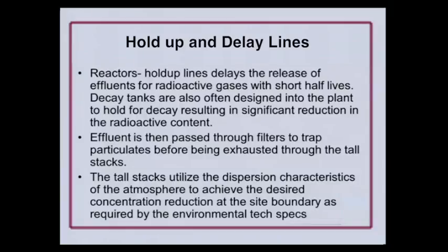The length of piping here is designed so that if I take an atom of radioactive xenon, and let's say it was born right here, it's at its max radioactivity. This is designed so that the time it takes to travel through here and reach this point, it's decayed enough that it can be fed up in here. And if it's not, then there's a shut-off valve, and it'll close it off. Yeah, that is correct.